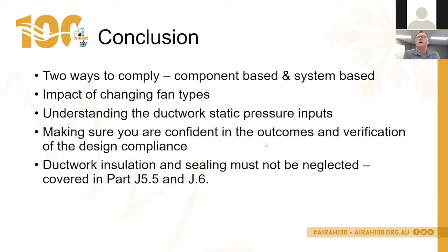However, the 2019 code addresses the issue with 2016 around the fact that some fans in the watts per litre per second tables, or some applications of fans, didn't actually have an available product that could meet compliance. So in some instances, you may find it to be slightly less strict for 2019, but overall it is more stringent and requires a higher efficiency.